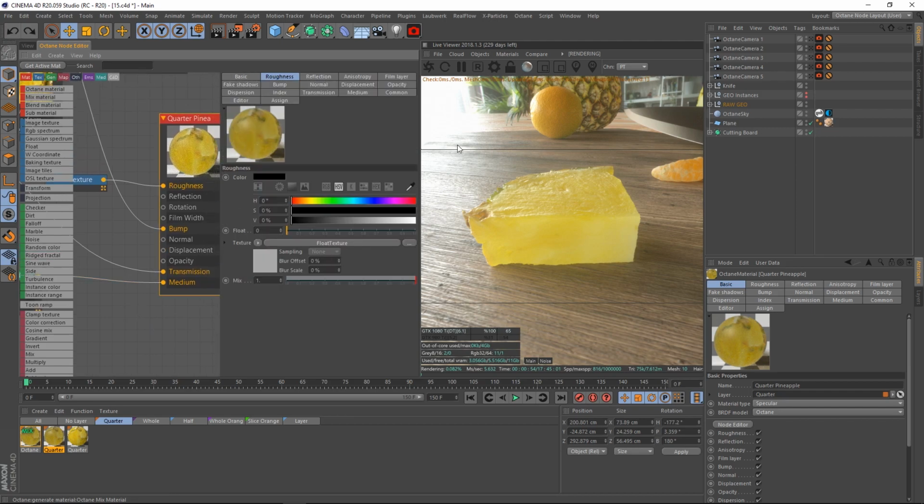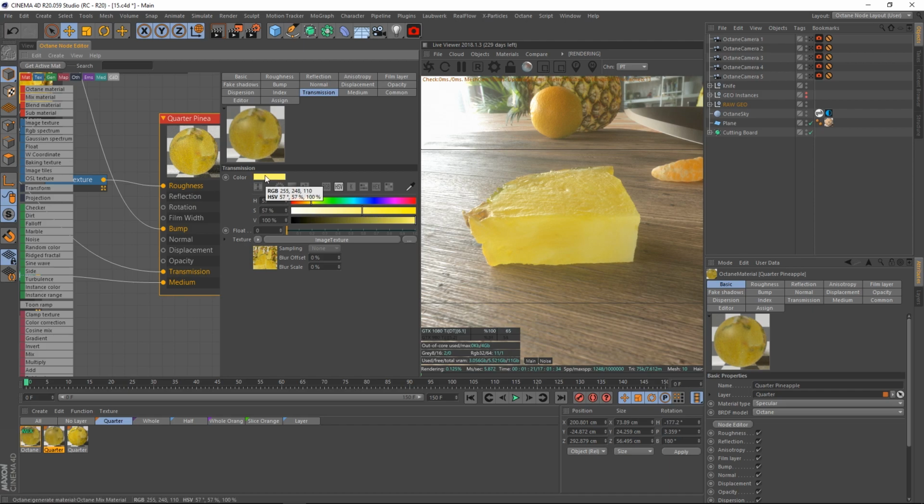And it's all about adjusting your transmission value based off of how much of the actual regular color is right out of the gate. So you always start, okay, what's our base color in this transparent object that we're looking at, right? What's our base color for the standard usual area for it? So we'd say, okay, maybe like a little yellow, this is our typical lemonade, and then anything that's really absorbed in more, we could then come up with an absorbed level of that. So that's usually how I like to work.